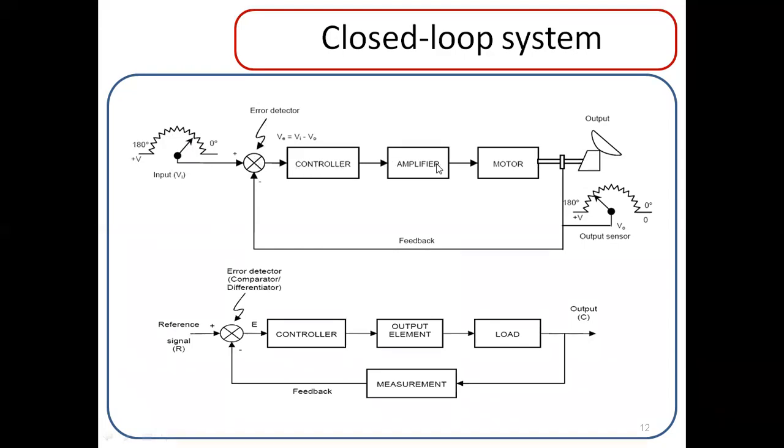the controller will give the signals to an amplifier, to amplify the electrical signals that are passed from the controller, and those electrical signals are necessary to actuate the motor at that particular capacity as per the input criteria. In the input conditions we are given that the motor has to rotate at 300 rpm. So to satisfy that 300 rpm, input conditions need to be maintained, that only at 10 or 20 amperes or 30 amperes of current need to be provided. So that needs to be maintained.